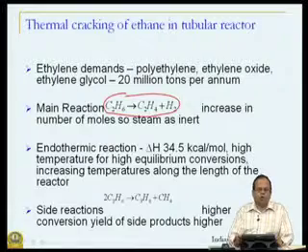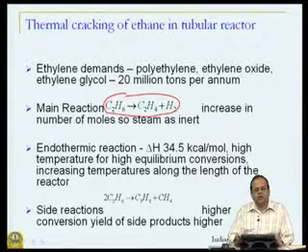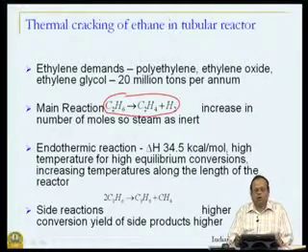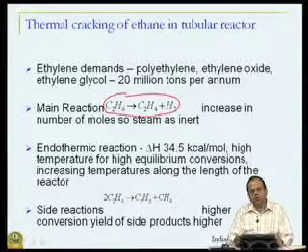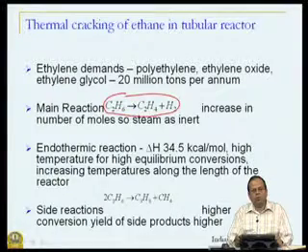Even if you do not want to increase the temperature, because this reaction is endothermic, as the reaction takes place and you are not trying to control the temperature, there will be a natural tendency for the temperature to go down, because the reaction will take away energy from the system. So, even otherwise we will have to somehow keep heating this system to maintain the isothermal temperature.